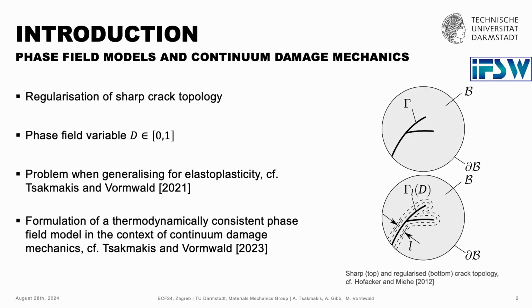Now, as not all of you might be familiar with phase field modeling, I want to give you a small introduction to the topic. So the point of departure is the classical linear elastic fracture mechanics, as it was originally proposed by Griffith. In that scenario, we have a discrete crack path with a discontinuity in the displacement field, and we have the intact material state within the bulk and the fully broken material state along this discrete crack path.